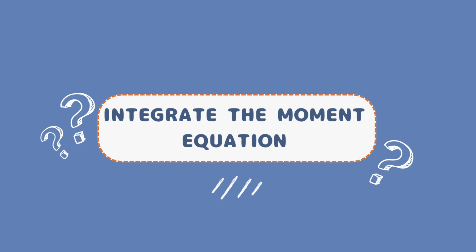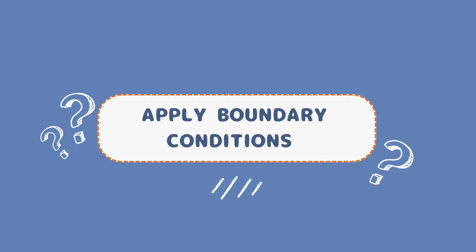Fourth, integrate the moment equation. Integrate the moment equation to find the slope and then integrate again to find the deflection. Lastly, apply boundary conditions. Use known deflection and slope conditions to solve for constants in the equations.